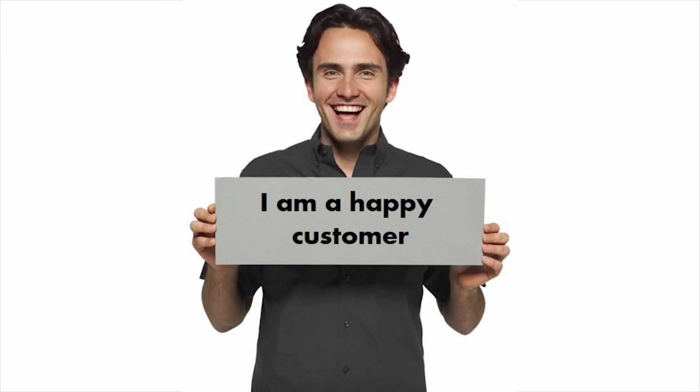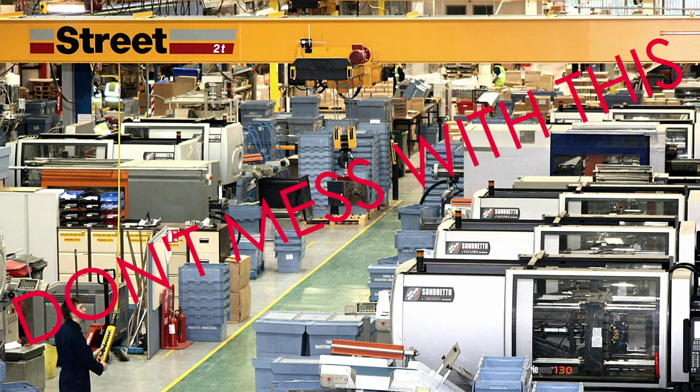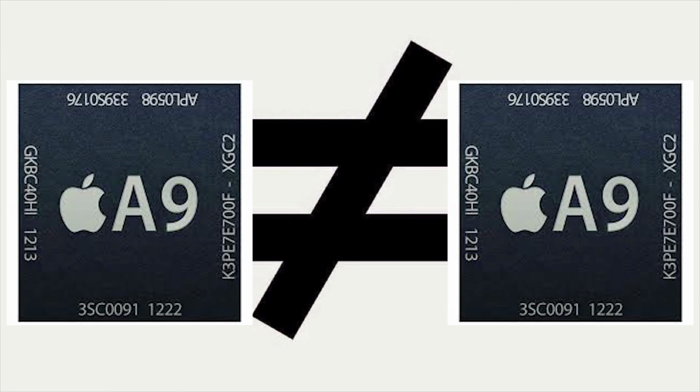Well, once Samsung's machines that are used to make the transistors are set and they are made to make a certain kind of transistor of a certain size, they only make that transistor. There is no prompt that asks you to input the size of the transistor that you want. The machine is made to construct 14 nanometer transistors, and it will only make that 14 nanometer transistor day in, day out. So this is why the two A9 CPUs are different and why they bench differently.